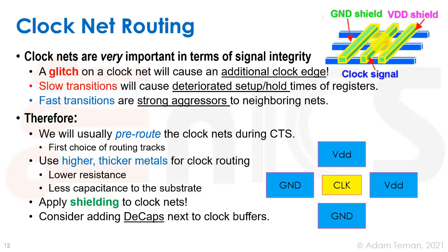It also shields the other signals from the clock, because remember, the clock has this really good transition, and that transition has high frequency harmonics, which are going to easily go through a capacitor and cause glitches on signals. But really, we want to mainly protect the clock tree.